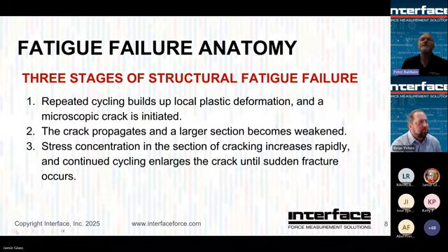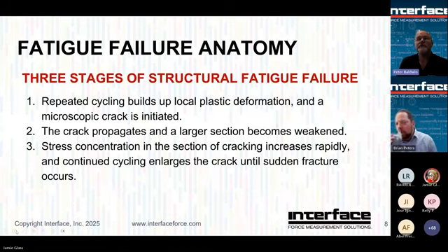Okay. There are three stages of structural fatigue failure. Repeated cycling builds up local plastic deformation and a microscopic crack is then initiated. As the test continues, that crack propagates and a larger section then becomes weakened. And then as the test further continues, the stress concentration at the crack increases rapidly and continued cycling enlarges the crack until there's a sudden fracture.